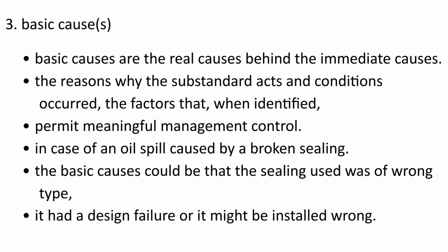In case of an oil spill caused by a broken sealing, the basic causes could be that the sealing used was of wrong type, it had a design failure, or it might be installed wrong.